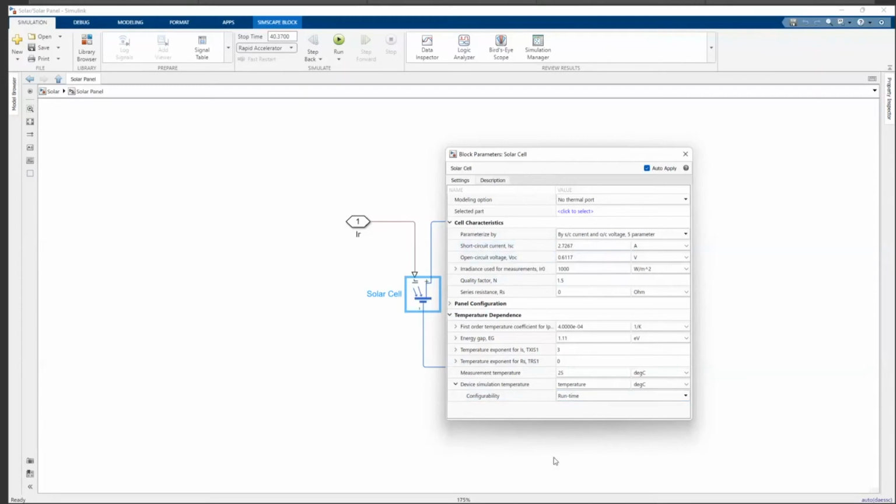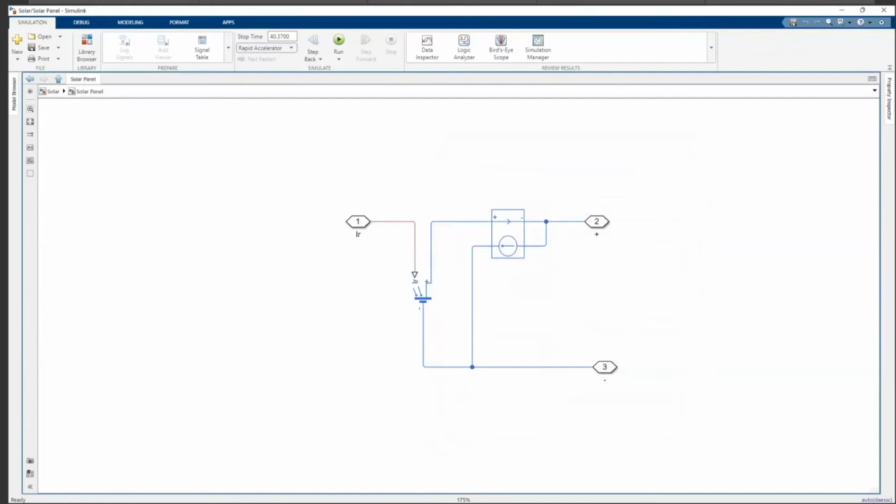So what I did in this case is, you have these options, compile time and runtime. I want to change the value of this temperature at runtime, so I select this as runtime here. By default, it will be compile time. This is one thing I didn't show.